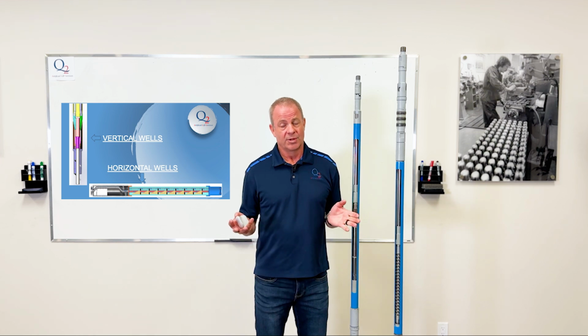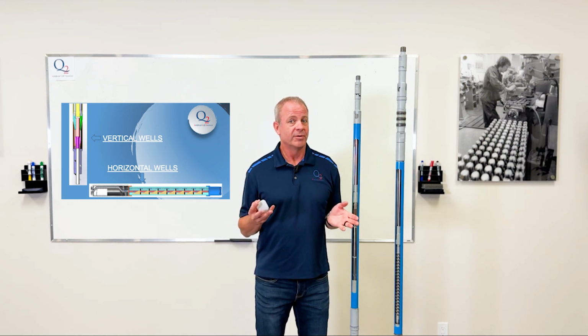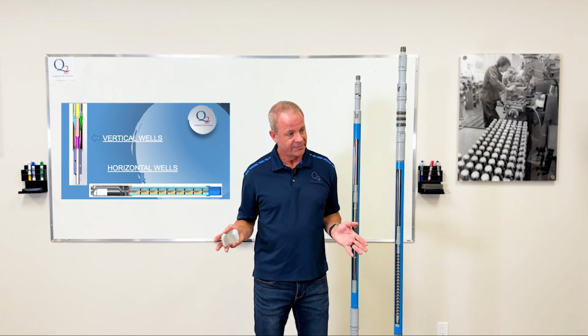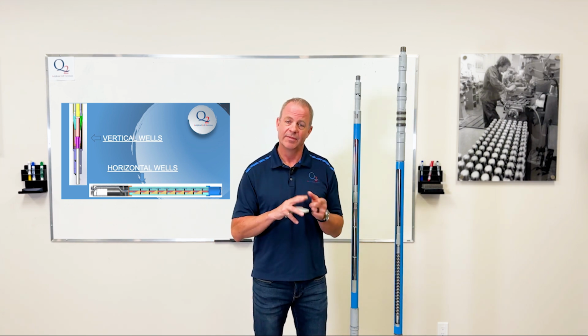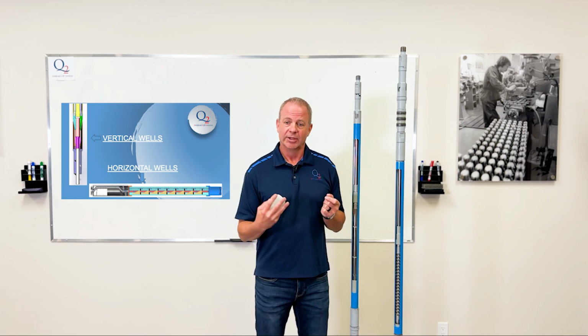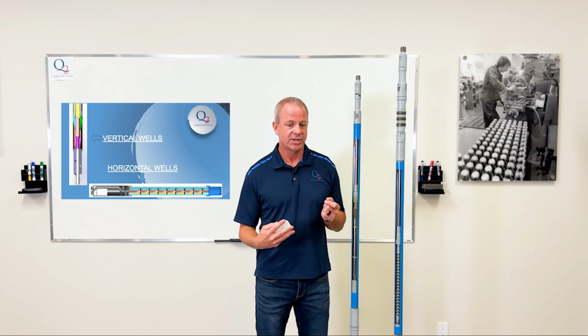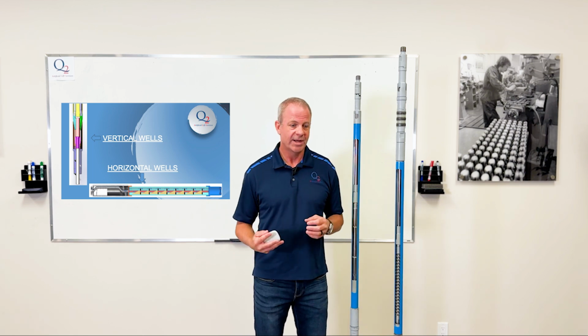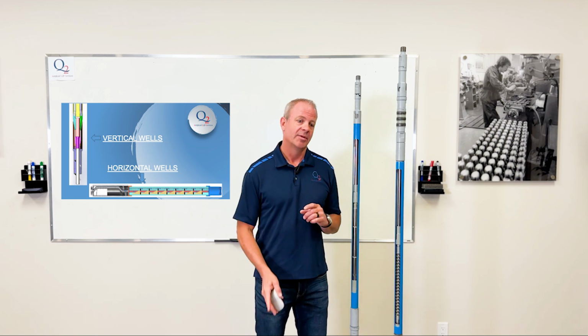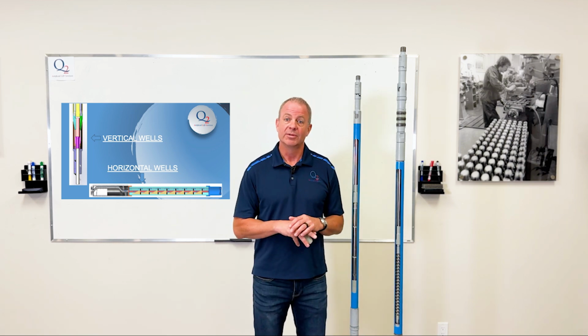It's pretty interesting. You've got vertical wells and your horizontal wells. When it comes down to the vertical wells, gas separation is really important with respect to solids if you've got high GLRs. First you separate the gas, number one, then you separate out the solids. In some cases, a little bit of spiral flow, maybe not too much centrifugal flow, but a little bit of a swirl vane is probably a good thing when it comes to separating out some of the solids and leaving something that you can pump up through the middle to the pump.